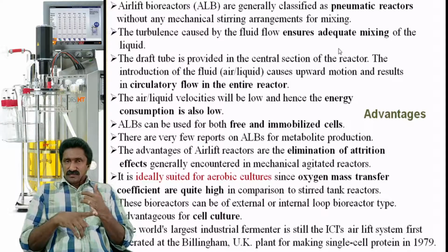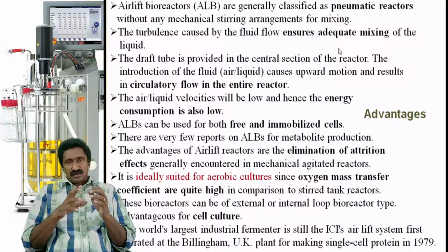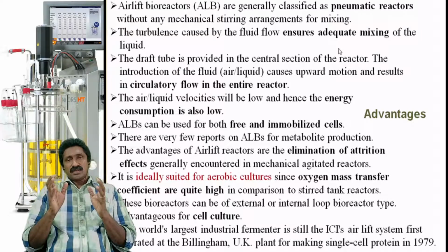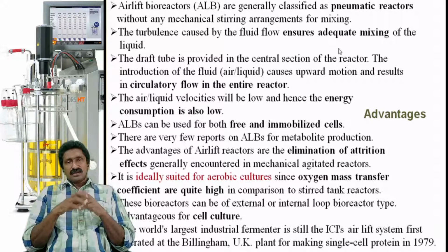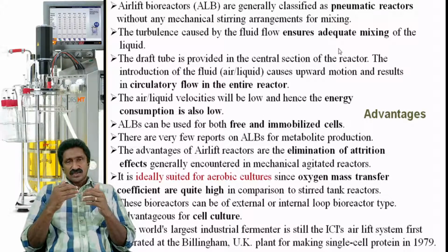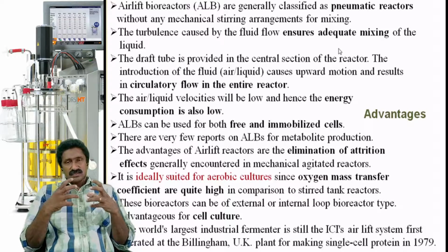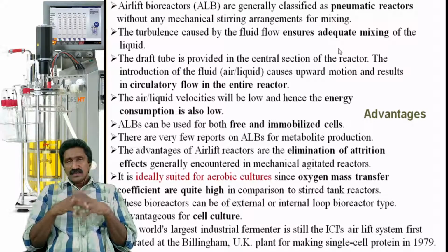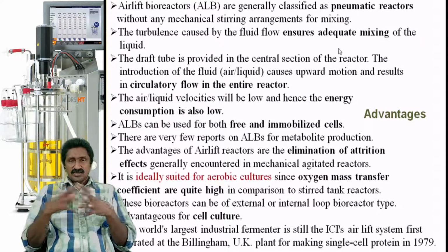Airlift bioreactors can be used for both free and immobilized cell systems. There are very few reports on airlift reactors for metabolite production. And the advantages of airlift reactors are the elimination of attrition effects generally encountered in mechanically agitated reactors. Means the mechanical stirring may cause many shearing effects or adverse effects on the cells, which will be minimized in airlift reactors because there is no such mechanical agitation and shearing.